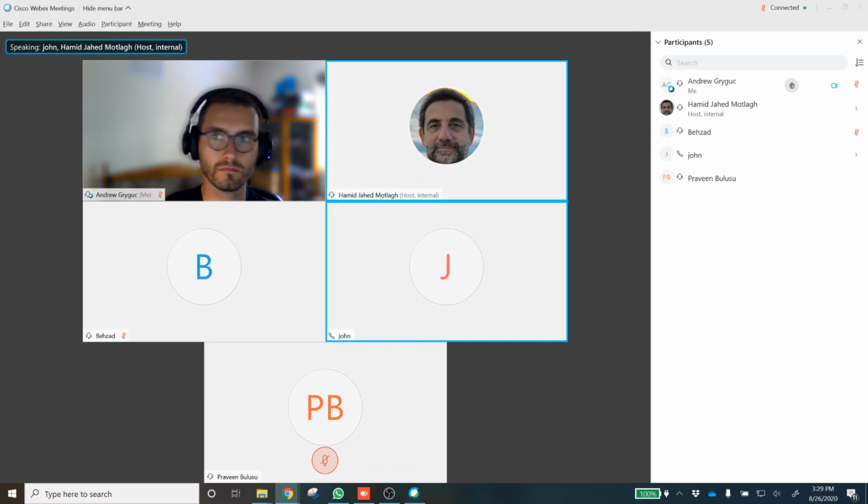Okay. Now, the original material, what type of material are we talking about? Is that a material that we do have the properties of already before case hardening? No, we don't. So basically, we need to do a standard strength test with and without case hardening on a couple of samples, say.